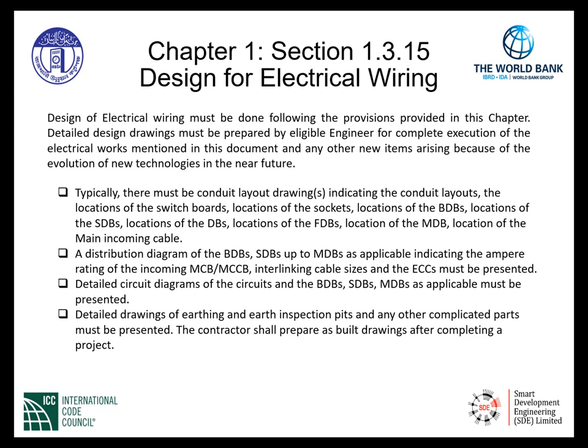Detailed circuit diagrams of the circuits and the distribution boards, as applicable, must be presented as well. Detailed drawings of earthing and earth inspection pits and any other complicated parts must be presented also. The contractor shall prepare as-built drawings after completing a project.